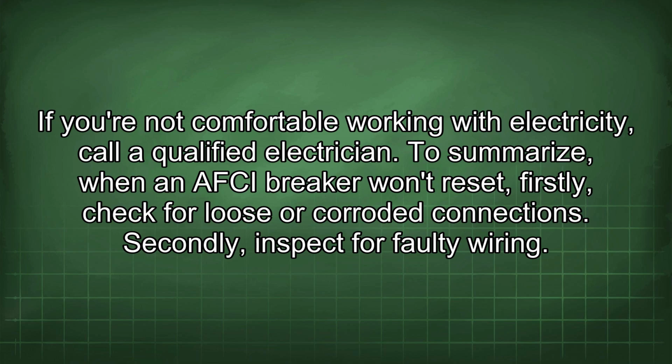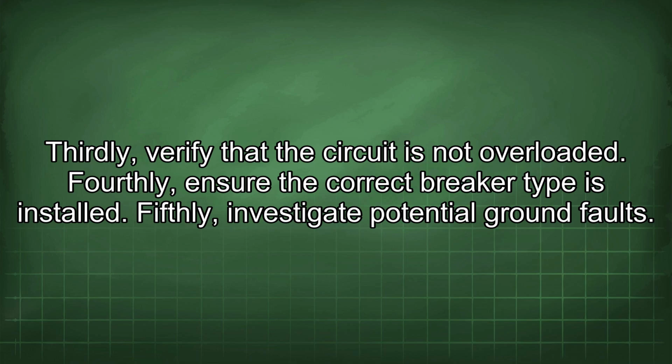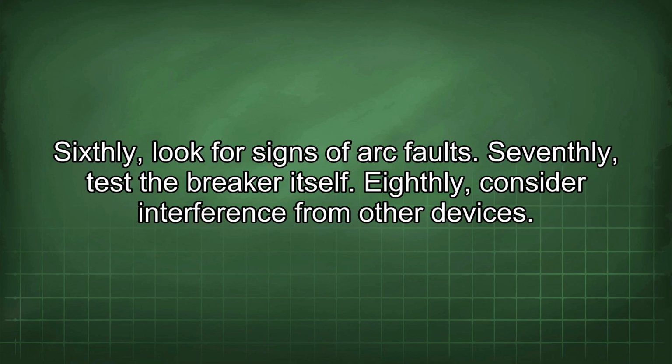To summarize, when an AFCI breaker won't reset, firstly, check for loose or corroded connections. Secondly, inspect for faulty wiring. Thirdly, verify that the circuit is not overloaded. Fourthly, ensure the correct breaker type is installed. Fifthly, investigate potential ground faults. Sixthly, look for signs of arc faults.